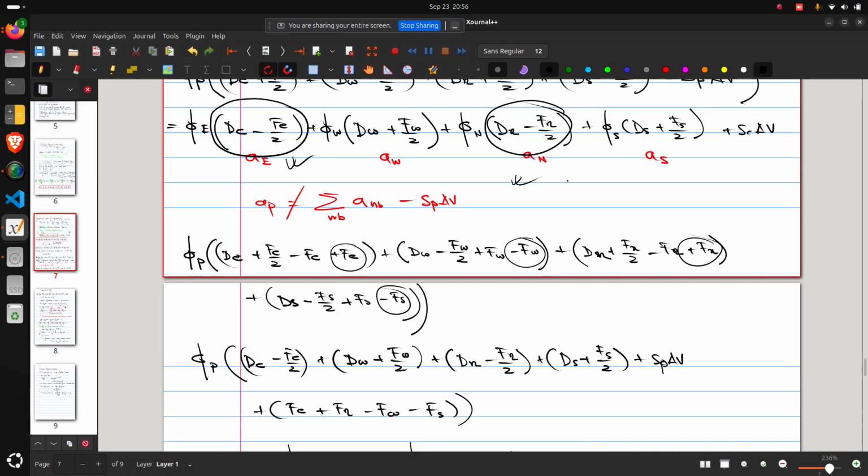So you average over the two cells that are shared by the face, and in the later part we will be introduced to the upwind scheme, which will help you to avoid the negative coefficients that appear in the A east and the A north terms,